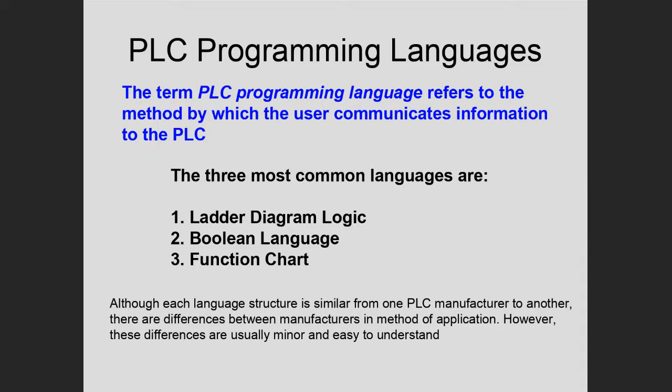Of course, the most common way is ladder logic, or relay ladder logic. This is where we have instructions designed to look like schematic symbols off an electrical diagram. When you write a program using ladder logic, it really looks like an electrical ladder diagram that an electrician can understand. In theory, you can give your program to a plant electrician, and he or she should be able to understand what's going on, even though they don't know PLC programming. It's close enough to an electrical schematic that they can basically see how the system functions.